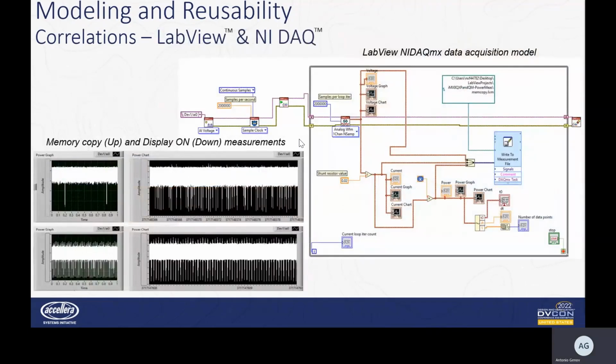In order to increase the correlation accuracy, we found a way to extract higher resolution measurements using National Instrument Data Acquisition hardware, and we have created a LabVIEW model allowing the extraction of voltage, current, and power consumption. We have configured the system to 1 million samples per second, and this resolution is still a lot lower than the one from our estimations, but it is better than the previous one. We can see more clearly some of the power profile variations, for example.